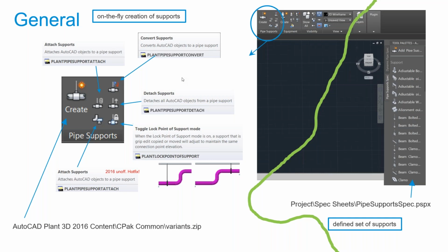Well, as you know, in Plant 3D we have orthos and we have isos. On the ISO, you will find information about the pipe support, that means the position and the description. We have the orthos, where you can put dimensions, where you can explain in the context of surrounding objects how this support shall be installed.